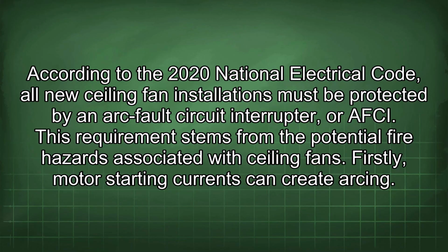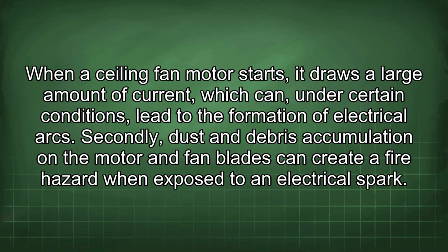According to the 2020 National Electrical Code, all new ceiling fan installations must be protected by an arc fault circuit interrupter, or AFCI. This requirement stems from the potential fire hazards associated with ceiling fans. Firstly, motor starting currents can create arcing. When a ceiling fan motor starts, it draws a large amount of current, which can, under certain conditions, lead to the formation of electrical arcs.